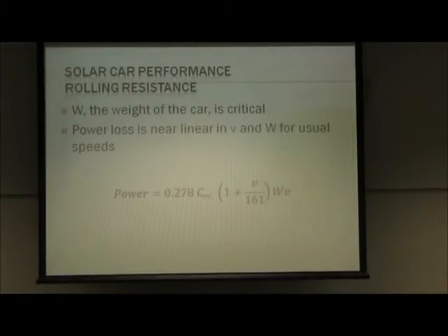Okay, rolling resistance. What is rolling resistance primarily? The resistance between the wheel and the road? Yeah, it's going to be the losses in the wheel. Why do you have losses in wheels and tires? They're flexing, just flexing. The bottom part is compressed, the top part's not. It flexes, it moves in it. And you've got that. You've also got one other loss. Where's the other loss? Bearings. Of course, in our car, we've got a third loss. What's the big third loss I've seen in your current car?